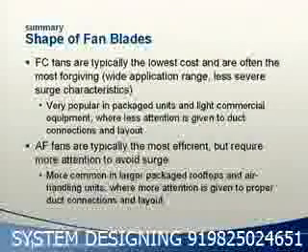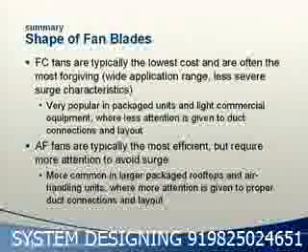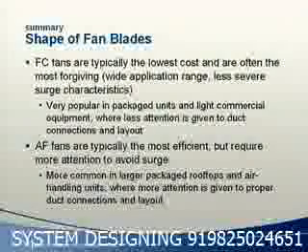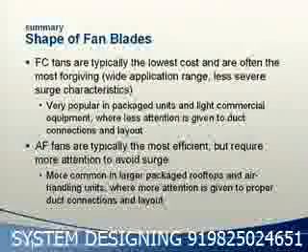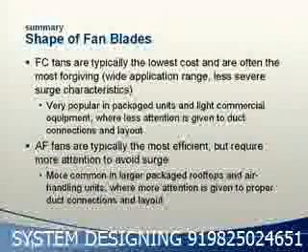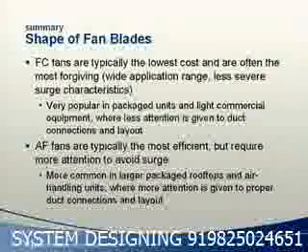Airfoil fans are typically the most efficient, but because of their narrower application range and their tendency to have more severe surge characteristics, they do require more attention to avoid problems. This makes them more common in larger package rooftops and applied air handling units, where more attention is usually given to proper duct connections and layout.